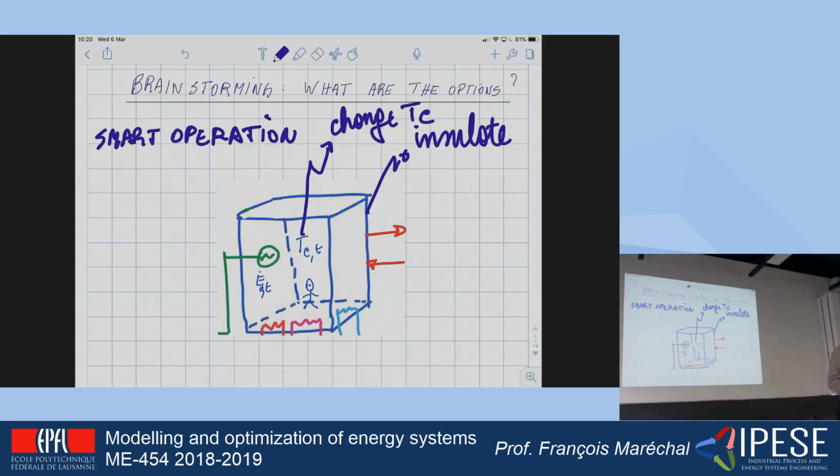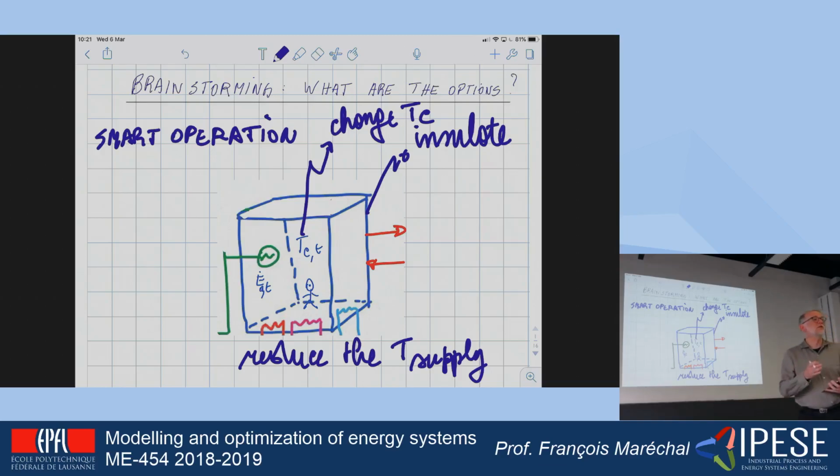If we increase the heat exchanger areas, we can reduce the supply temperature. Reduce the supply temperature, yeah. What would be the benefit of reducing the supply temperature? We need to heat the supply less, and for example the heat exchanger would be more efficient because it has a smaller delta T. So you would like to reduce the supply temperature. In fact, you do not have to increase the size of the radiators.